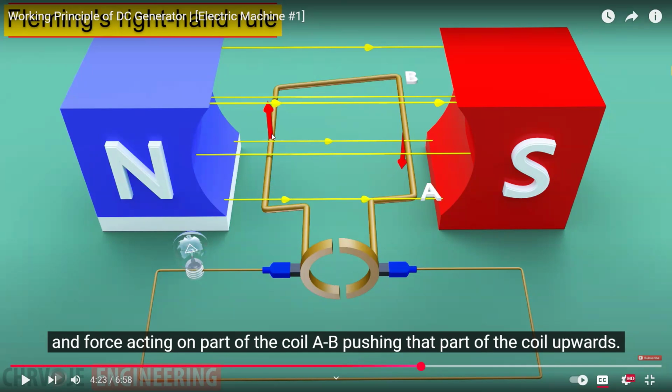And due to every conductor, if you have current flowing in this direction, for instance, into the page like that, in the direction of my cursor to the top, then the flux direction will rotate around the conductor using the right-hand or thumb rule. From the thumb rule, you will find the flux rotating around the conductor like that. From the top side, it will be in the same direction as the flux moving from north pole to south pole, and from the south side, it will be in the opposite direction.